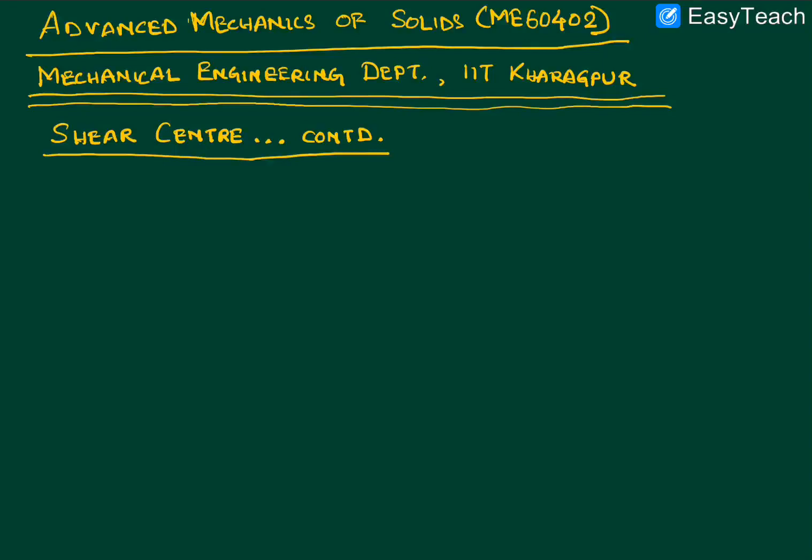Now, in addition to that, what we'll also need is that the cross sections will have to be of an open nature. So the cross sections that we'll be considering will be thin walled open sections, and as I had mentioned in the previous lecture, this has direct importance, immediate relevance for structural mechanics, because many of the cross sections like the Z section, the L section, the T section, the I section, they're all exactly like that. They are thin walled, and they also have an open structural form.